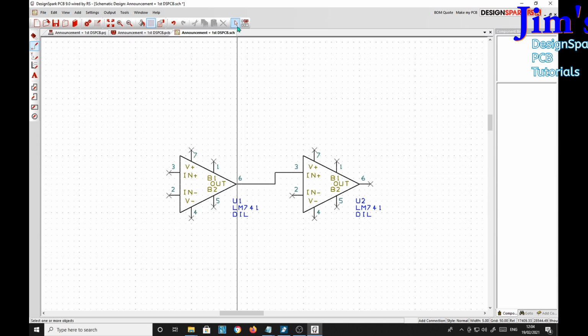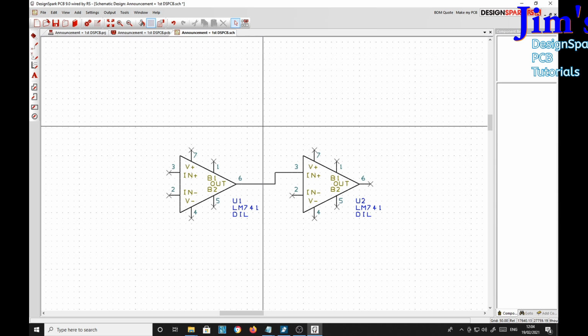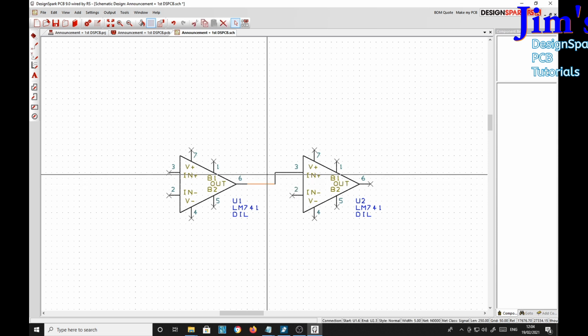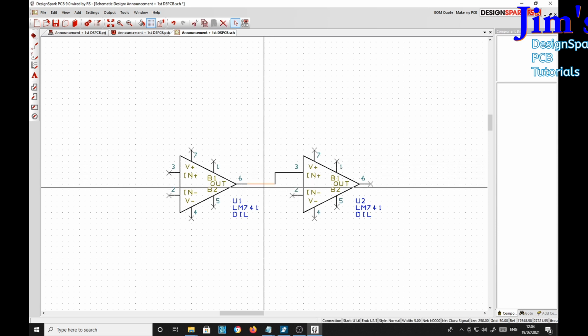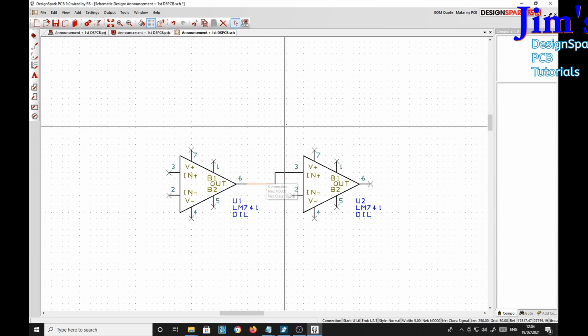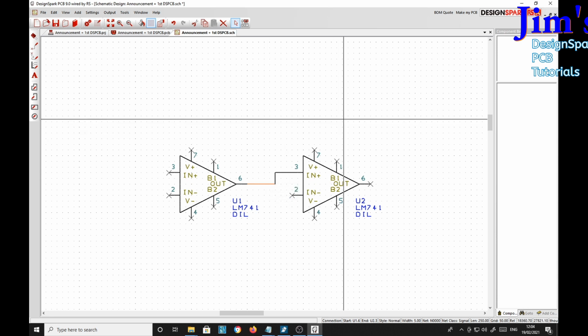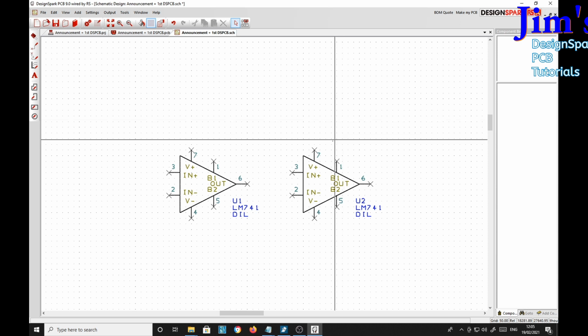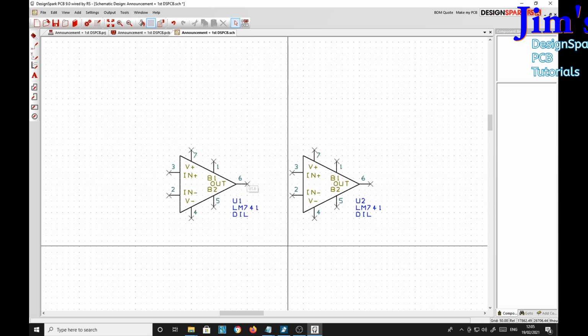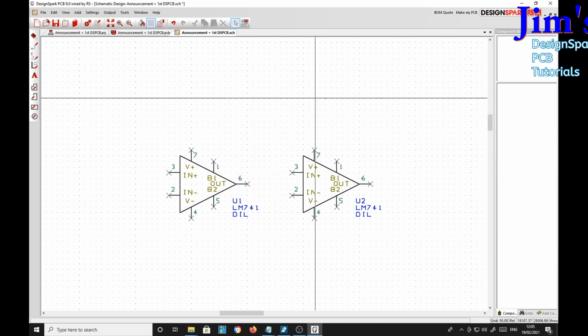So if we go back to up here, select mode, select one of these parts of the net, this net here. If you hover, you'll see that connection N0000, net class signal. Nice. If we delete it, all of the net gets deleted, not just that part, and the connections come back, which is perfect.